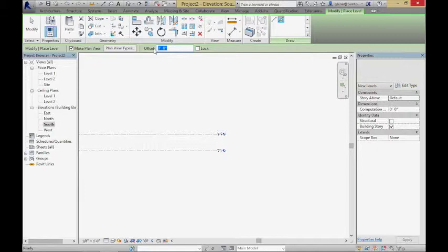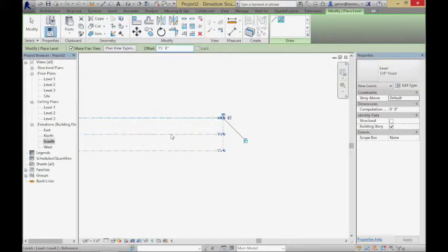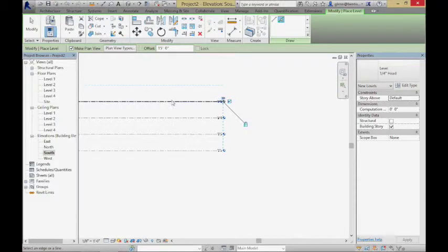So here's what I always like about offsetting. I can pick a line, but I'm going to duplicate something that's a set distance away, like 15 feet. So the nice thing then is I can hover, and every time I'm clicking, notice it's creating a new floor level for me. So over in the floor plans, we're getting a new floor level. And it's creating new levels.